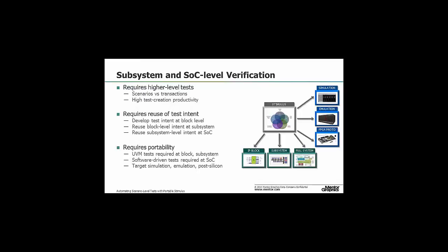At SOC level, it's simply not realistic to try to reach full coverage. Instead, people tend to focus more on interesting scenarios that need to be verified, corner cases or situations, rather than individual transactions. And since these scenarios are much more complex and can encompass many transactions, you need to be more productive when you create them, otherwise it will take forever.